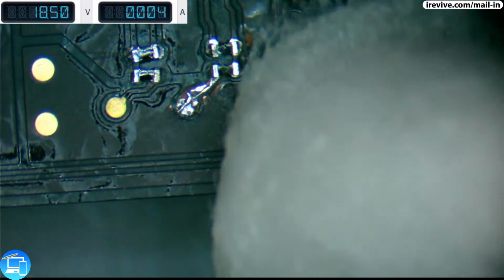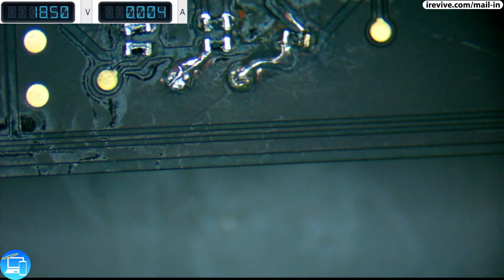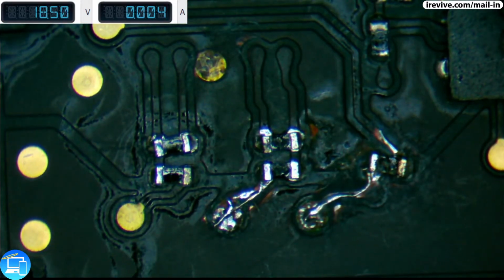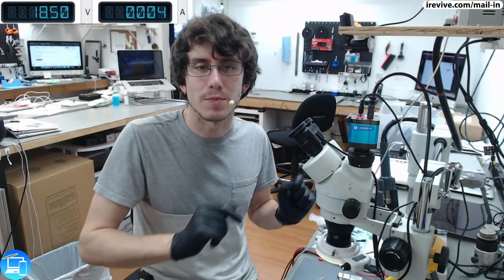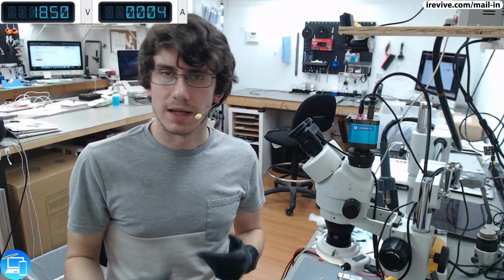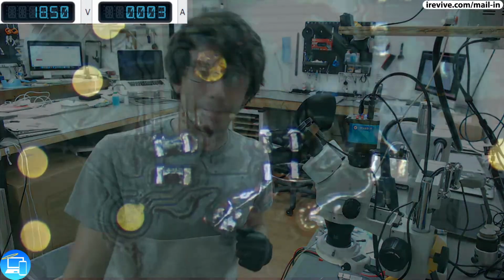Okay, our resistors are there. Now, we're going to beautify them. We're going to make them look pretty. Because you can see they're crooked, and it probably works, but I really don't want this customer to come back in the future, so I'm going to apply a little bit of solder onto each pad just using our micro pencil. And then I'm going to use the rework station so that we can kind of melt it all together and it looks nice and pretty when we're all done.